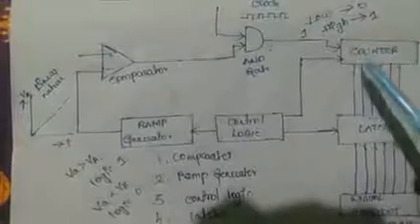Here a decoder converts n inputs to 2 power n outputs, but we have different input and output ports, that is the latches and the display unit. For the purpose of matching, we need to use a decoder. When the clock pulse applied to the counter is 0, it stops counting. If the clock pulse applied to the counter is high, it counts and stores the clock pulses in the latches. The stored value in the counter is displayed in the display unit.